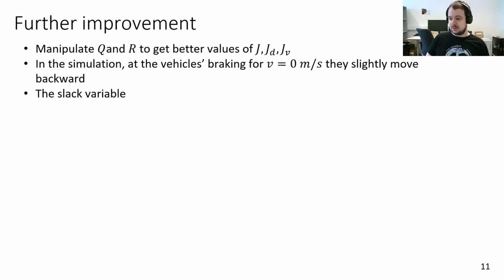the distance following is as best as possible. But the velocity penalization in a certain sense works as a damping that mitigates the differences between the simulation and the actual physical system. So in this case, we could improve the behavior in the real life experiment by increasing the penalization of the velocity. Or we could also introduce the soft constraints using the slack variable.